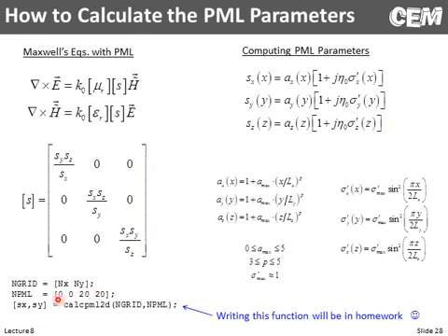So clearly, for some reason, we don't want a PML on the x-axis boundaries, but we do want a PML on the y-axis boundaries, and we're going to make it 20 cells each. So you hand those arguments to this function you're going to write called calc_PML2D, or calculate the perfectly matched layer for 2 dimensions, and it will hand back Sx and Sy. In this case, there's no S sub z coming out because this is just 2 dimensions. We're in the xy plane. So that'll be a homework assignment, to write that function. And all the equations you need are on this slide. And I'll also provide exact values for P and A max and sigma max that you'll need.